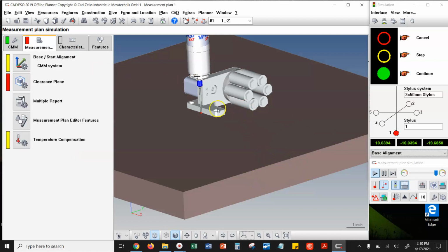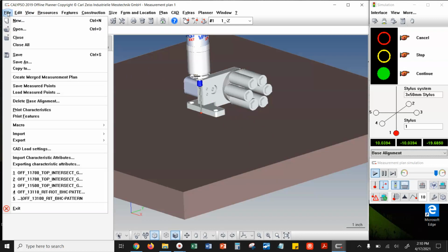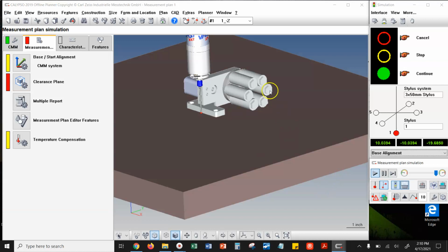Here's another thing I recommend to you. I recommend that you go File, Save, and save often. Basically, save after every command. And if you can, save as a different name, like save it as whatever the file name is, -1. On your next save it as whatever it is, -2. And that way, even if you have 15 files, by the time you get a successful CAD transformation, well, you can just delete the first 14 and then delete that dash number off the end of the file, and nobody knows the difference.